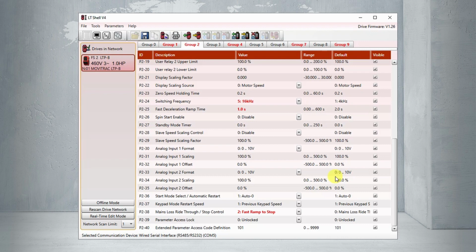My VFD now says inhibit on it, and I'm going to factory default it. Just a reminder, whenever you factory default the VFD and then you load the parameters in, the very first thing it's going to do when you try to run it the first time is try to auto-tune itself. So my VFD is going to auto-tune at the very end when I try to run it. So don't forget that. Always remember auto-tuning will be in the picture if you factory default your VFD.